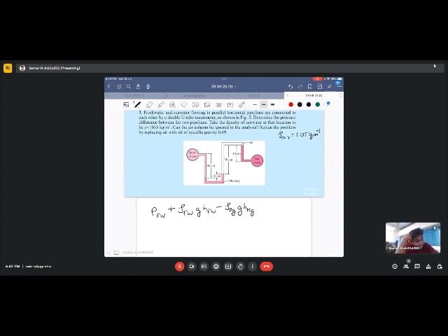Now there is an air column of 70 centimeters, so that's again the opposite, upward direction. ρ_air g h_air, and h_air is 70 centimeters. Now we can disregard the pressure at these two points since they are in static equilibrium. Therefore we can go downwards from this point onwards and add the